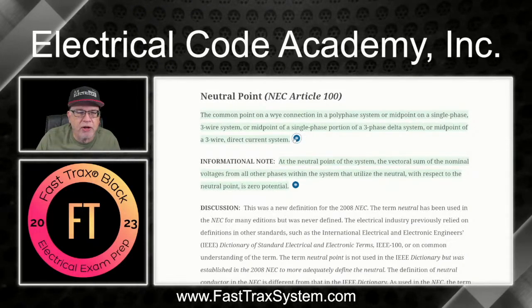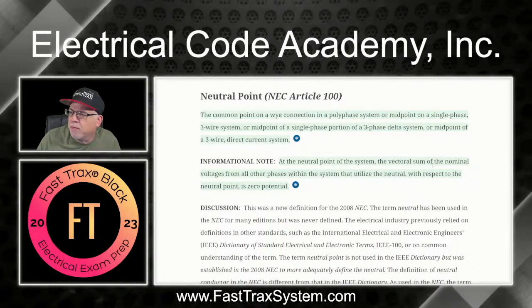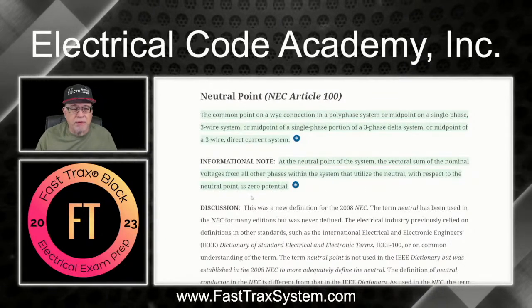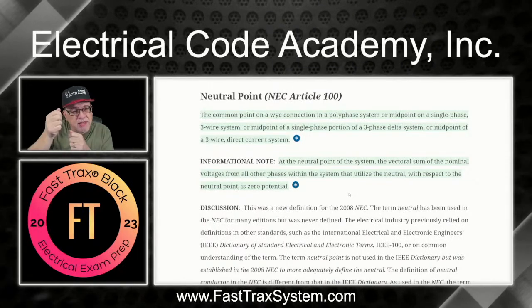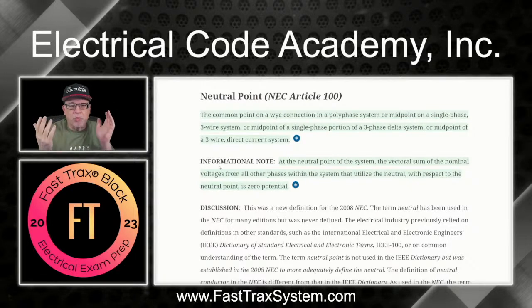Now, this little asterisk right here in our course just reminds you that this is verbatim out of the National Electrical Code. And then, of course, you have an informational note that says at the neutral point of a system, the vectorial sum of the nominal voltages from all other phases within the system that utilize the neutral with respect to the neutral point is zero potential, okay? So wherever you're making a connection in our system from the neutral point to all other phases, you're using the neutral point to get that reference, and it's considered the zero connection. And that's also how we get stability in reading our voltages. Again, this is an informational note. It's not enforceable, it's just information.